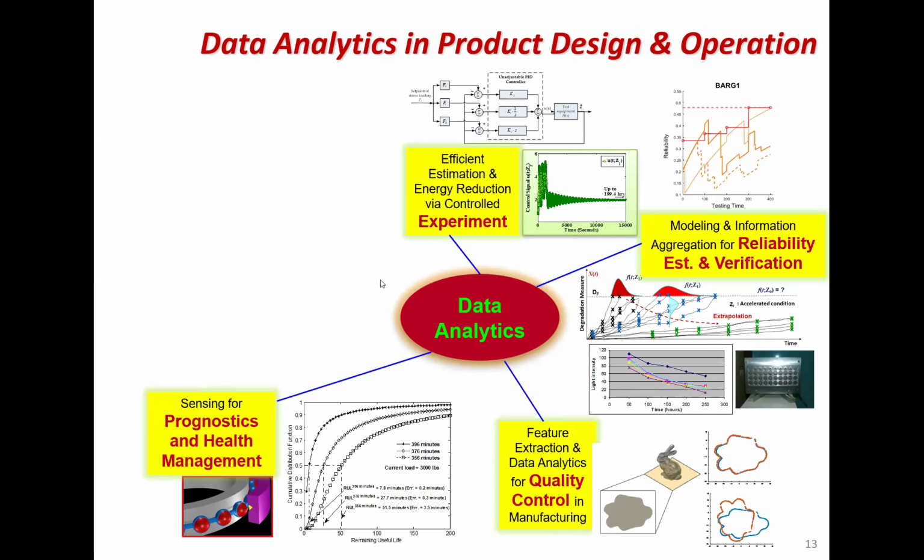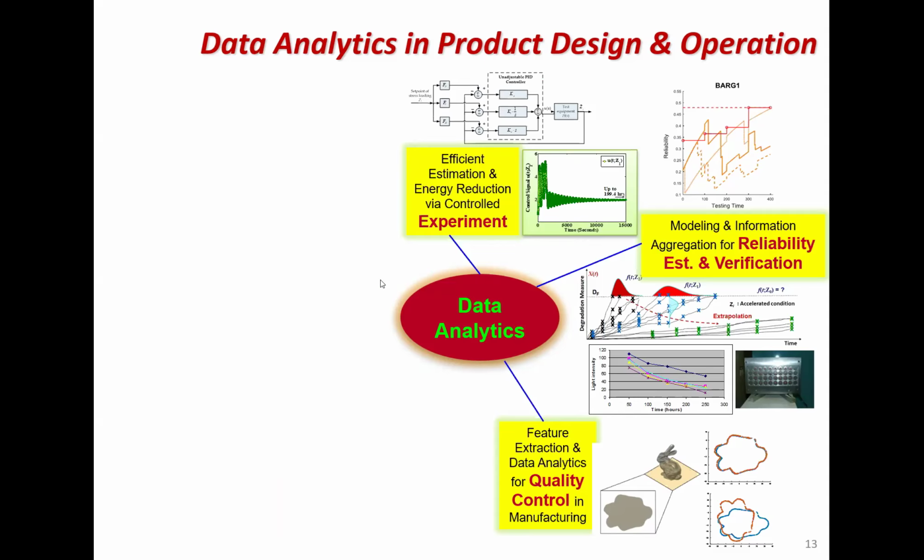So basically they collect sensor data and put sensors on some individual system and keep monitoring health index or signals. So they use the health index to quantify the system health and also predict the remaining useful life of the operating system. Just before the failure occurs, they can actually provide some useful information so that we can do maintenance as early as possible and also at the right time and the right place.